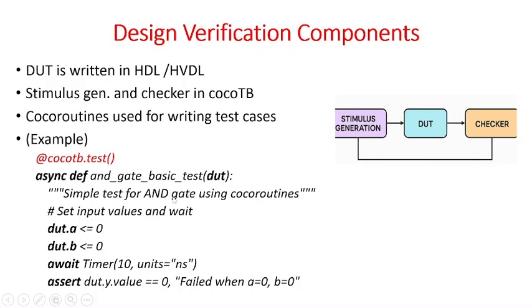Right. Now we use a handle called dut. This is a fixed one; we have to use it as dut only. It's a handle supported in CocoTB. With the handle, we can access various objects. The dut handle allows us to utilize the IO ports of the DUT as objects: dut.a, dut.b, dut.c. A and B may be inputs or outputs. When you are forcing a value to that particular object, dut.a equal to 0, that means you are applying some input to A. That means the coroutine is going to output a value which is going to be the input to the DUT's A input.